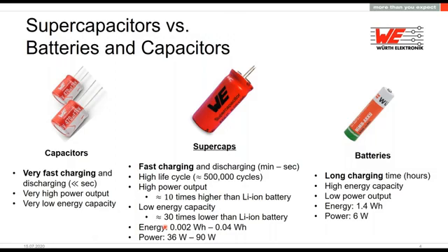But of course, every technology has some limitations. For the supercapacitor, it is the low energy capacity. It's around 30 times lower than a lithium-ion battery, and they have a linear voltage dependency. When you draw energy out of a supercapacitor, the voltage falls linearly. But I will show you this also later.